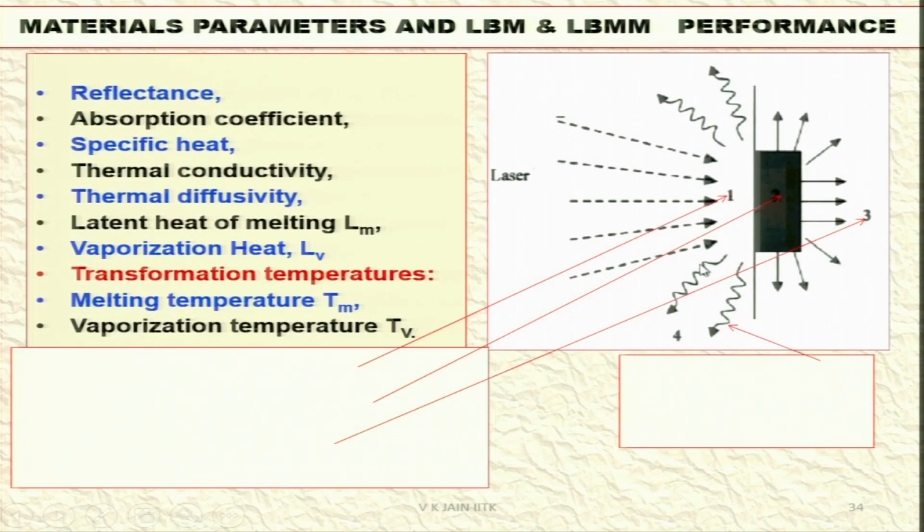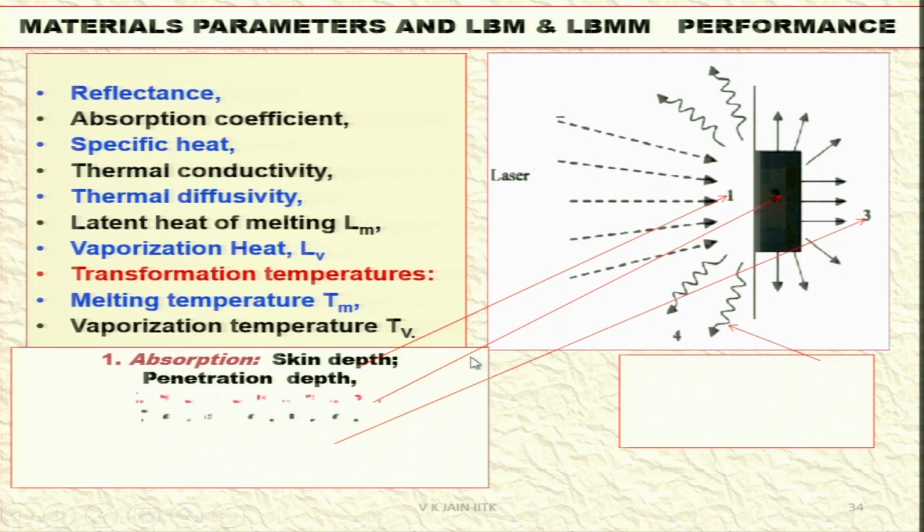You can see here laser is going on the workpiece surface, and you can see different phenomena taking place. Absorption, skin depth, penetration depth, absorption is taking place of this laser beam or light. Heat transportation, thermal conduction is taking place in this workpiece surface.